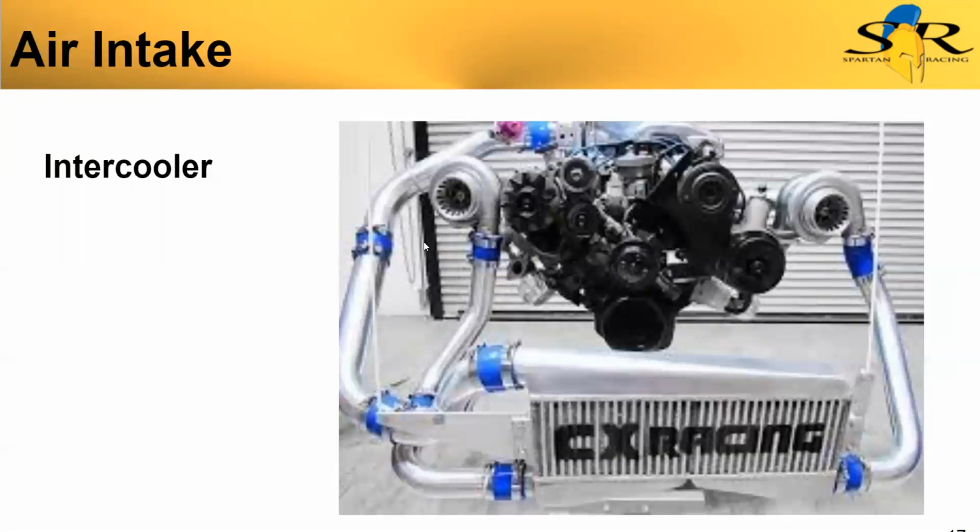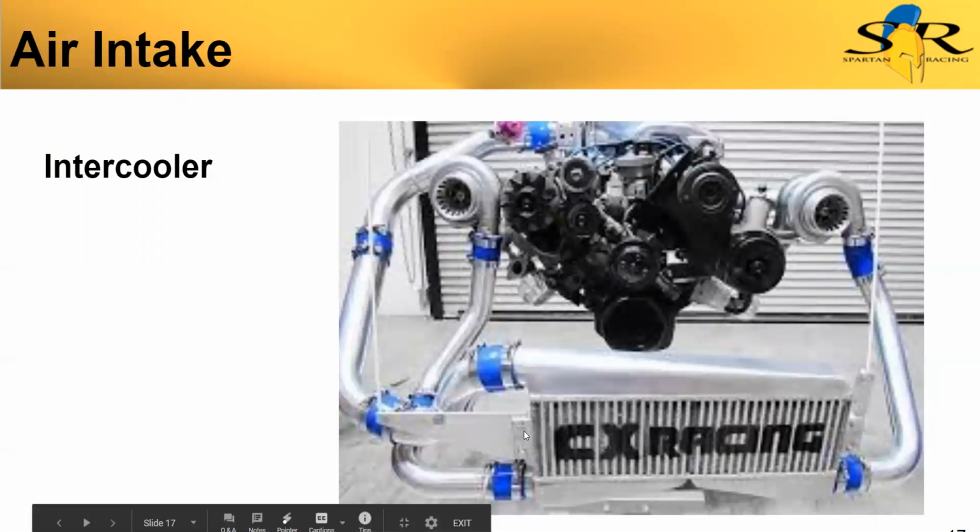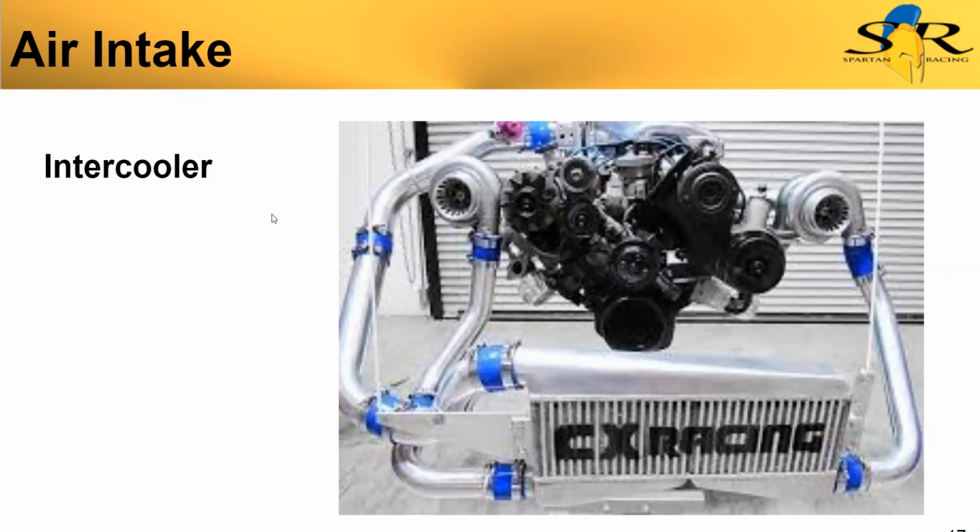There's air intake cooling. This is done for forced induction. Turbos create a lot of heat, because compressing the air creates heat, and then just because they're driven off the exhaust, that also adds a lot of heat. So they want to cool that air back down before it goes into the engine, so it gets dense and they can pack as much air into the engine as possible.